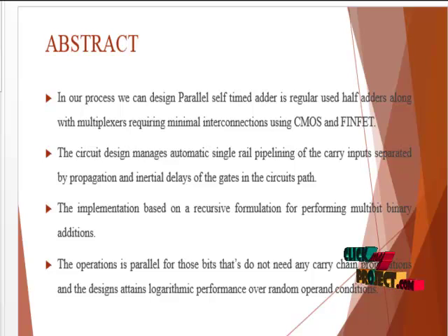So in our process, mainly we have considered pipelined adders using the single-rail data encoding process using CMOS devices in the FinFET process. The circuit design is mostly established for the flow of carry signals. In most cases, dual rail carry conversion is used for the internal bitwise flow of the carry outputs.